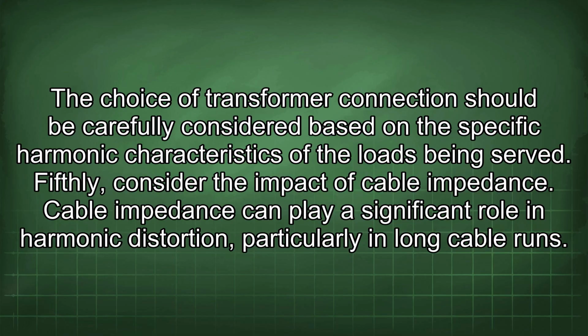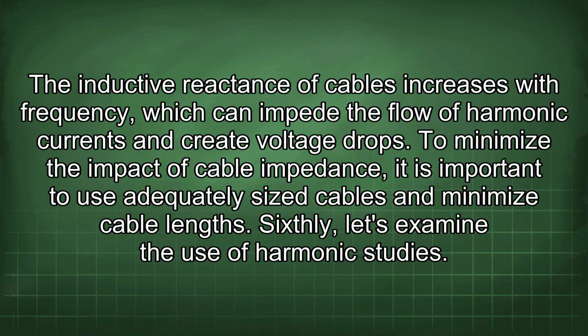Fifthly, consider the impact of cable impedance. Cable impedance can play a significant role in harmonic distortion, particularly in long cable runs. The inductive reactance of cables increases with frequency, which can impede the flow of harmonic currents and create voltage drops. To minimize the impact of cable impedance, it is important to use adequately sized cables and minimize cable lengths.